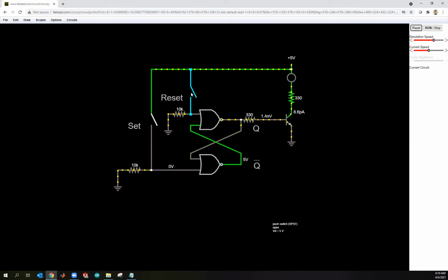And you can see that, right? I hope you can see that this is a memory in action. Notice the Q is like the memory. It's 1 bit that toggles high or low, and it stays there. It doesn't go away. So if I had a square wave coming into the set, a little square wave, it's going to set this bit of memory high. If I have a square wave coming into the reset, it's going to drop that Q low. And so I hope you can see that the LED or the Q is going high and then going low. Very simple action, right?